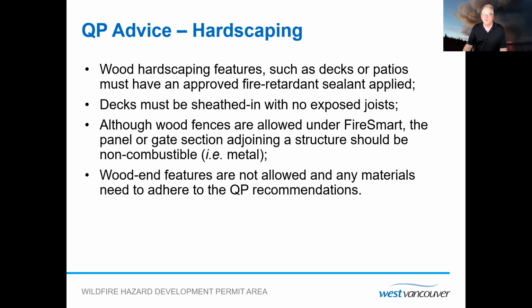Hardscaping, obviously, wood hardscaping features such as decks or patios must have an approved fire retardant sealant applied. They must be rated, as I talked to you earlier. Decks are another important thing in the FireSmart principles. We don't want open decking that is not rated. So the decks are enclosed. Simplest way is to sheath it in and incorporate with the siding that's used on the main structure.